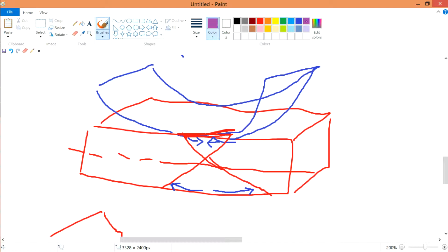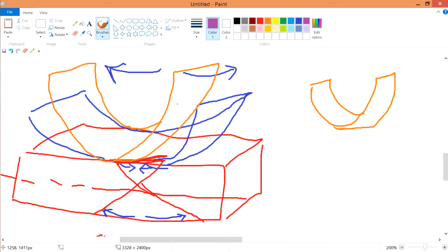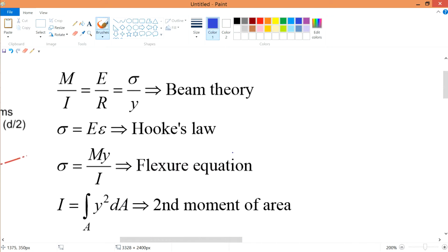And the next second layer, if you were to further pull it, when it reaches its yield strength, it will start to go somewhat like this. So this part here will actually flow in this manner, they actually crumple. That's why you see the shape became like this.